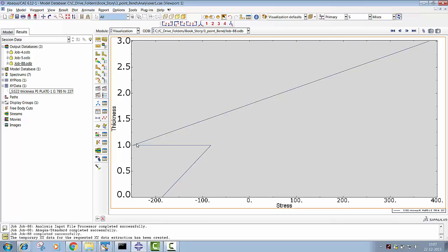So the resistance goes up and the corresponding stresses go high, and it reaches up to somewhere around 220 MPa in negative, that is a compression mode, and there is a linear transition from compression to tension bending stress, and somewhere the neutral axis is in this place. So this is how we have to interpret the through thickness bending stress results.